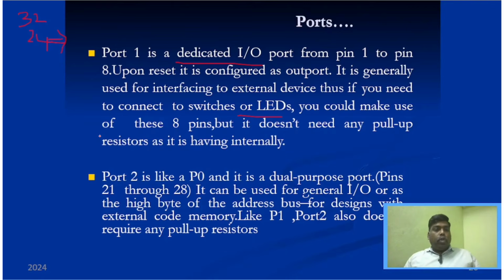Similarly, port 2 is once again dual purpose. Whenever I say dual purpose, it means it can act as an input output port, and it can also be configured as control lines, address bus, or data bus.